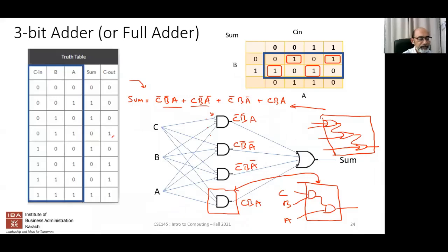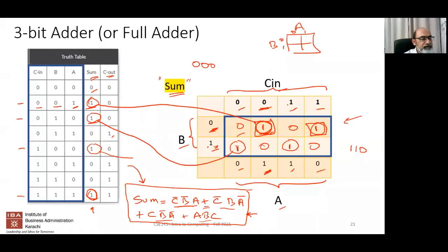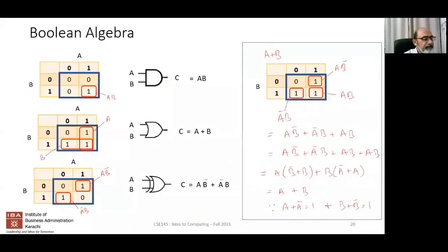So now the question is, why did we introduce the Karnaugh maps? Well, it did help us, hopefully, to visualize these particular scenarios. As you can see over here, each one of these terms corresponds to an independent cell. But the Karnaugh map comes in when you try to simplify things. So for example, in some cases, you could see that here the expression C is equal to A plus B. The reason why it made sense, and we didn't have to have the detailed expression, is because we combined some of these cells.